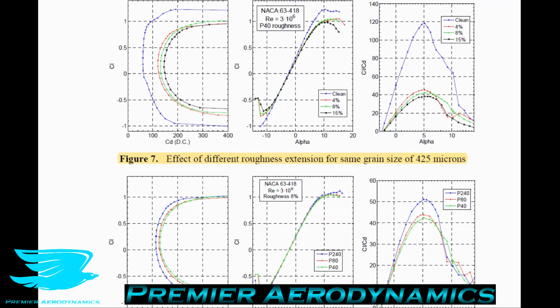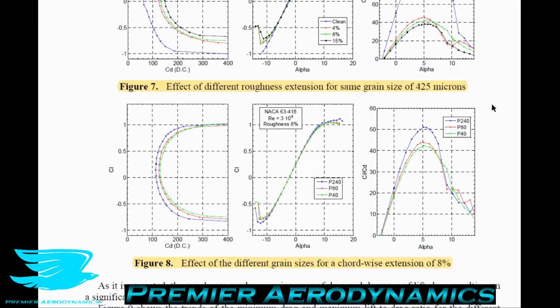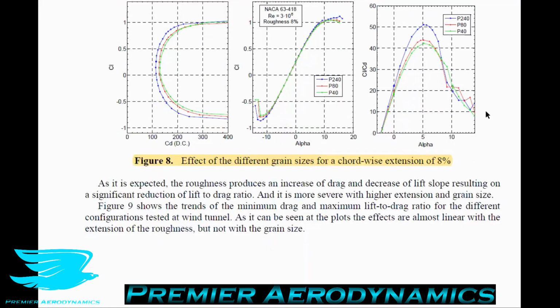And I guess you could extend that to a lot of airfoils, saying that these surface roughnesses generally would not be very good. However, as I mentioned, some boundary layer tripping is actually very good for keeping flow attached at higher angles of attack, so it could benefit stall. Just in this case, for some reason, they didn't find that. It might be for this particular airfoil.